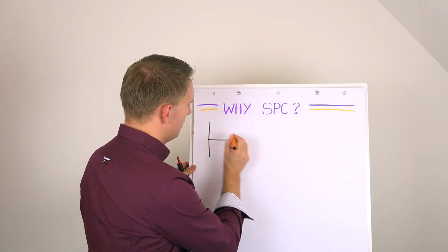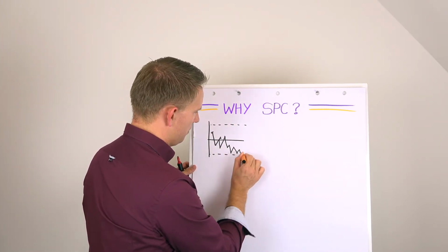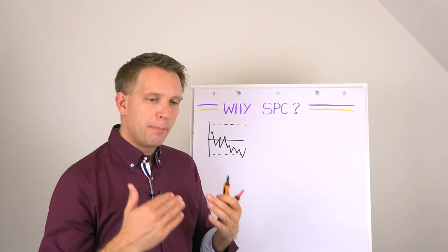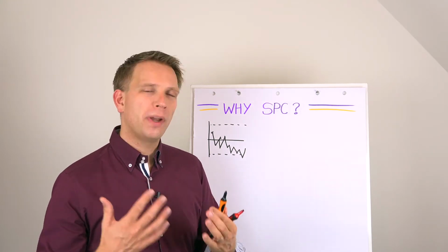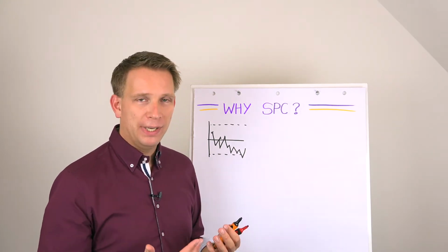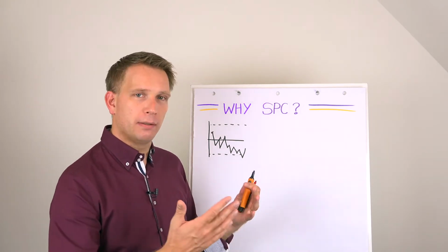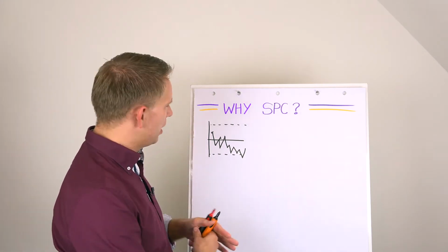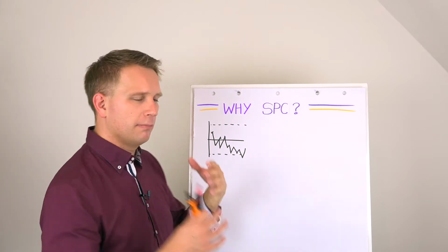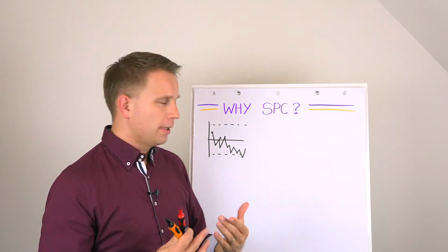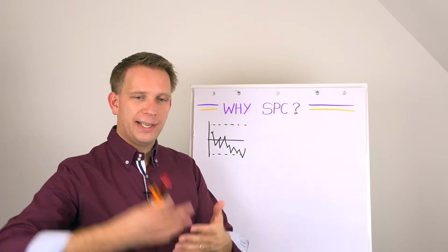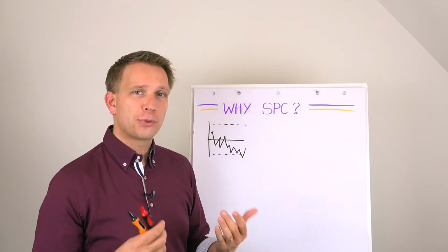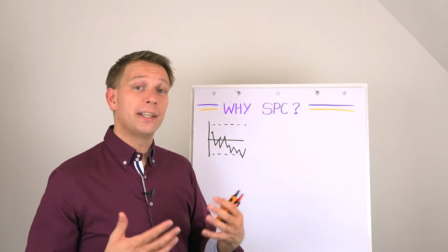What we have is a process that we monitor. We are measuring one thing in a process, which can, for instance, be the weight of some product coming out of our machine. And from history, we know that there is a certain average weight that comes out of this process. And we also know that if we take plenty of historical data, there is a sort of natural spread. And this natural spread we express in standard deviations.